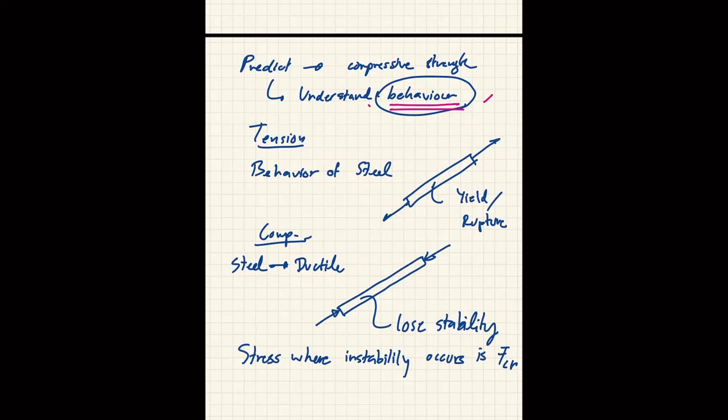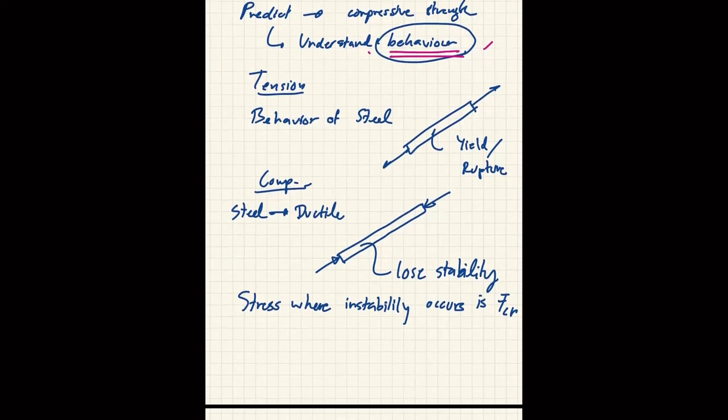You can see from the video clip that when you apply compression to the material, it sort of moves to the side, as if it was being bent, as if there was bending moment applied to it, and that is correct. When the member moves to the side under the influence of the compression, we call that behavior buckling. It's called buckling, when the instability under compression occurs.